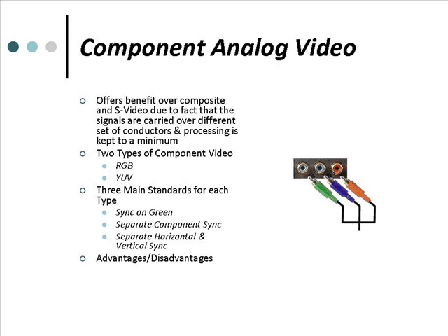and vertical synchronization. Separate composite sync uses a 4th signal path to carry the synchronization data, including both the horizontal and the vertical synchronization. Separate horizontal and vertical sync uses a total of 5 signal paths, one for each color signal, one for horizontal, and one for vertical. This system is used in virtually all computer monitors and is part of the original VGA de facto standard.